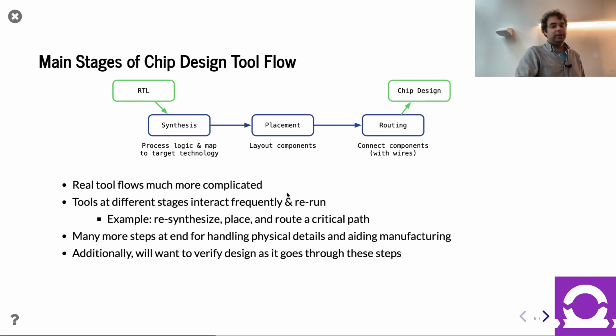And so, yeah, this is just to get the first design, but honestly, you have a lot more steps. There's a lot of concerns. For example, how do you make a chip such that when it's being manufactured, the factory can quickly check to make sure it was correctly manufactured, right? So designing for test, DFT, right? It also turns out, of course, when you're designing for high volume products and you have a very advanced feature node, even just manufacturing a chip requires changes to the design to make it possible to manufacture. That's referred to as DFM, or design for manufacturing. So there's a whole bunch of complexities there.